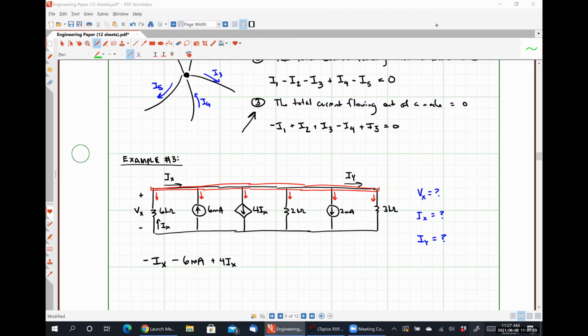So this 2 kilo ohm resistor is going to be a little bit tricky. And so I am going to argue that it will be easiest to use Ohm's law to develop a relationship for it. The reason I say that is because while we don't know what the voltage drop over that particular resistor is, like we don't have a numerical value for it, we do have a variable that already describes it.